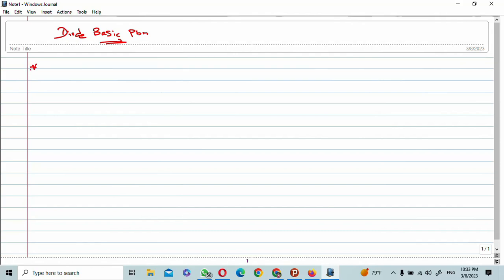The first problem: a one-diode circuit with one potential, then one resistor with a grounded load, a 5k resistor in series. We are going to find V0. The circuit uses a silicon diode.